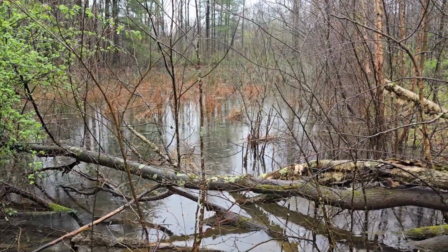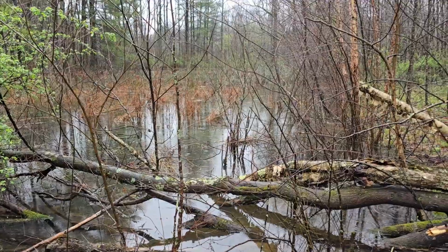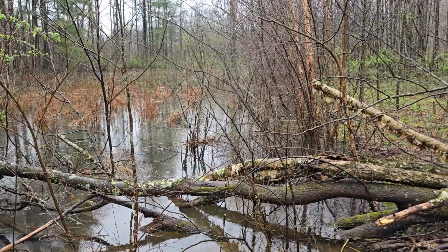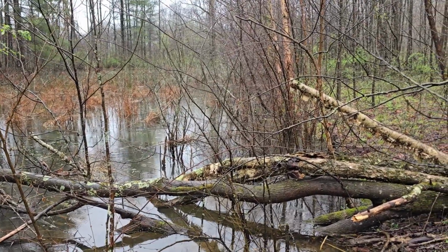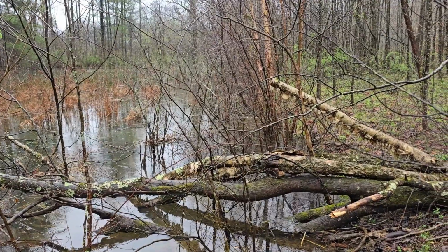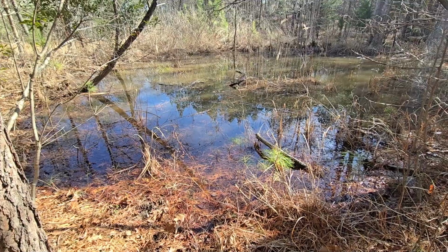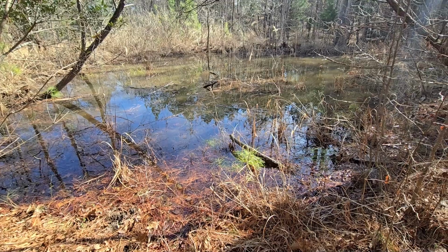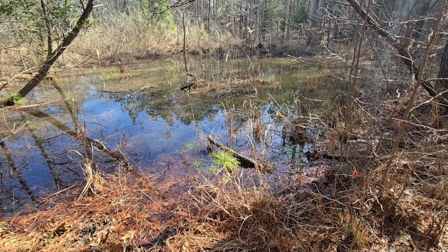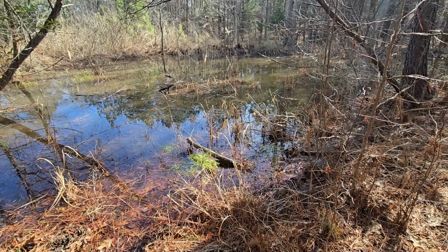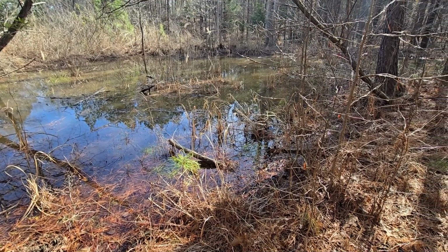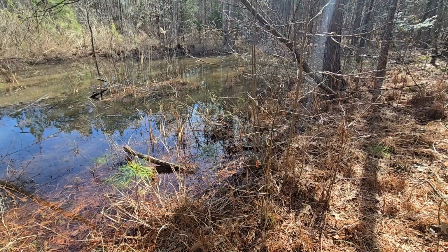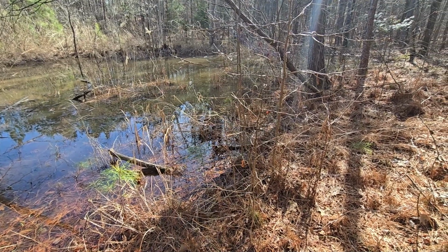It's possible to build dams that will last for years, like the dam we built for this wetland over 25 years ago. Remember that it's important to inspect the dam, the spillway, and the water control structure several times each year and take immediate action to complete repairs. We built this wetland at Harbison State Forest in Columbia, South Carolina during a wetland workshop 21 years ago. The dam is only 18 inches high and it has a wide top with gradual 5% slopes. The spillway is also wide and carries overflow in a sheet-like pattern down a gradual slope. The dam and the spillway have never been maintained.